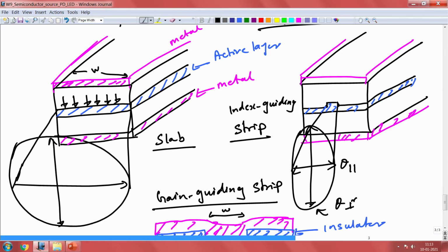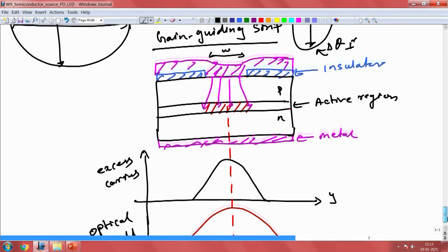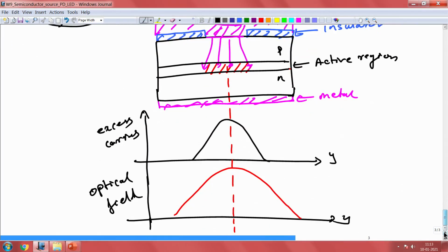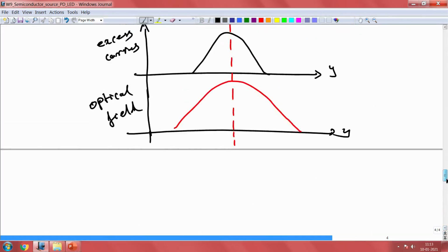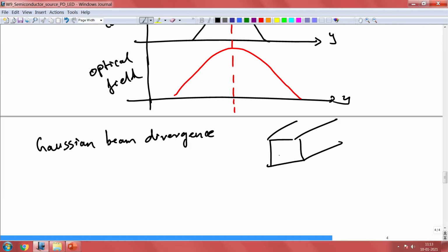And this particular divergence, in this case this is just the delta here, the Gaussian beam divergence in a guided system. Gaussian beam divergence particularly happens when you have edge emitting structures, right. When you have a waveguide here, the light is going to come out in an asymmetric fashion, right.